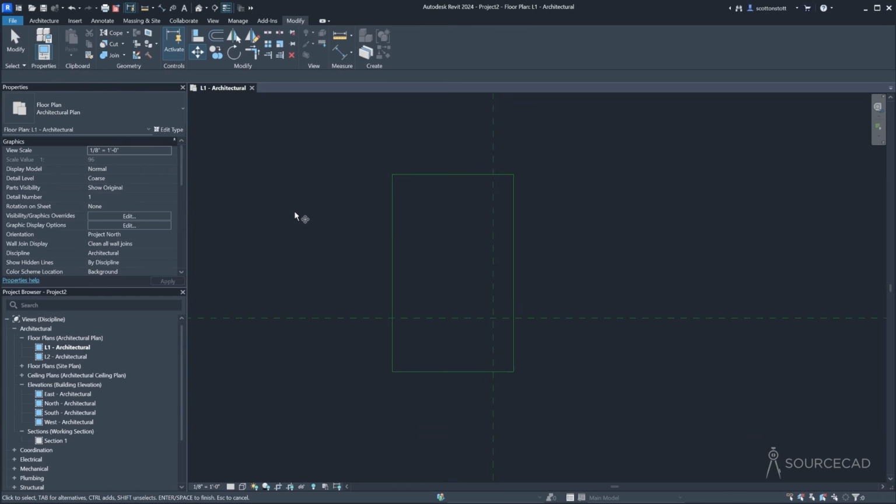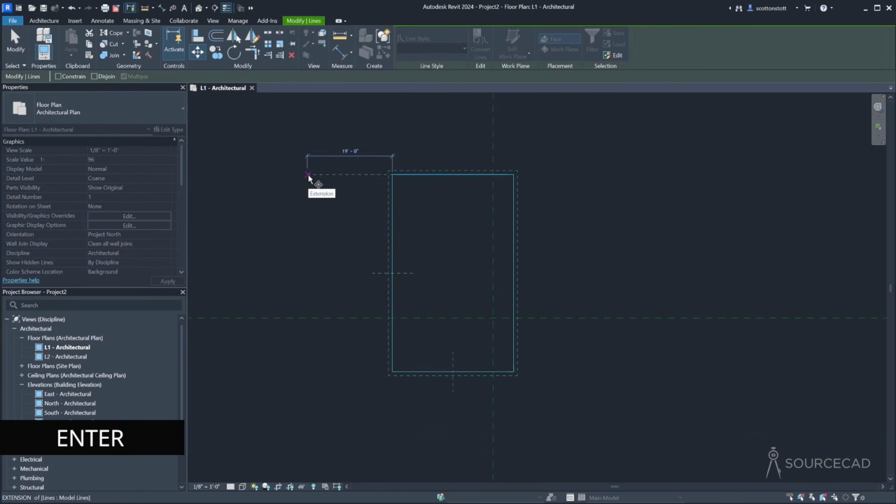And that message that appeared in the tooltip is also down here on the status bar. So you can read it down here. And it's important when you're first learning Revit, especially, to read what it says on the status bar, because it will give you a clue about what Revit is looking for. So evidently what it's looking for is for me to select something to modify. So I would have to select this stuff, and then I could modify it. And I'd have to press Enter or space, finish my selection, and then I could actually move it.